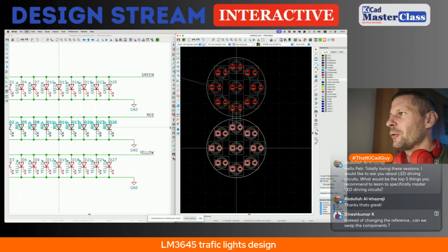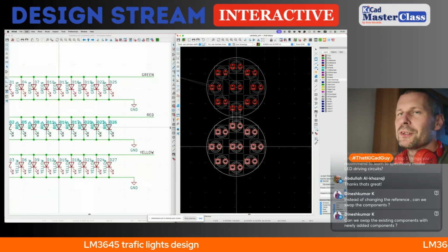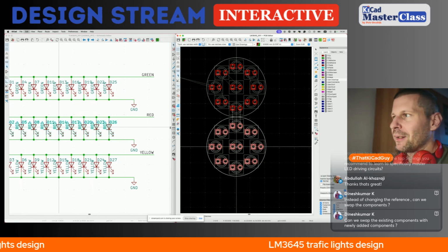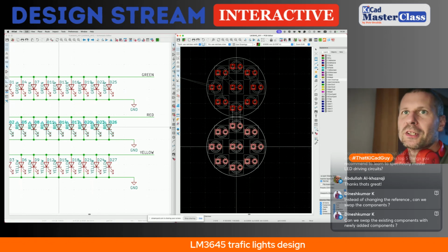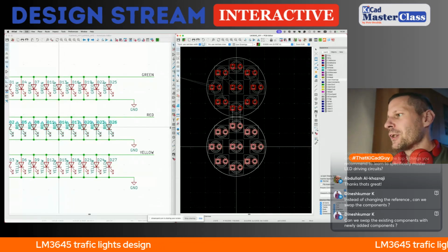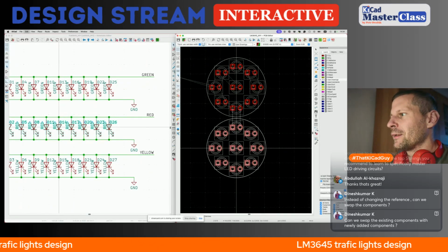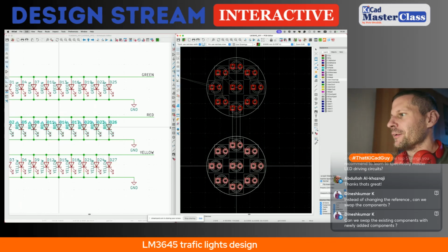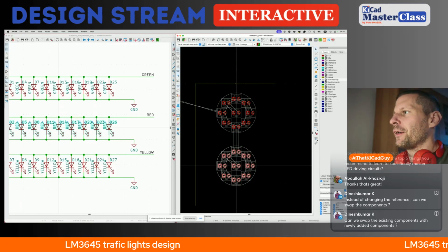So you can see that I have glued the components on my cursor. Now I'm pressing space, and the auxiliary scale at the bottom of the screen is zeroed, and now I'm moving 6 millimeters, 6.5 or 7. 6.5 is fine.